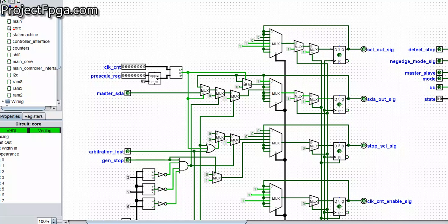After the initial state when it's high, it first sends a low bit, then it latches it here, then the next one it sends a 1 and a 0. So this is more like a start bit pattern: a 1, next a 0, then a 0 because it latched it, then a 1 and a 0.